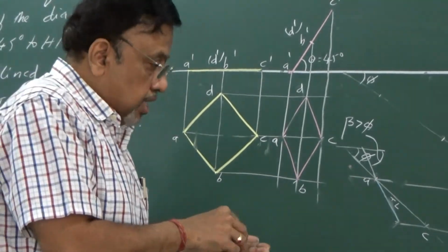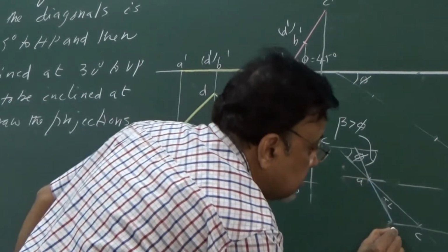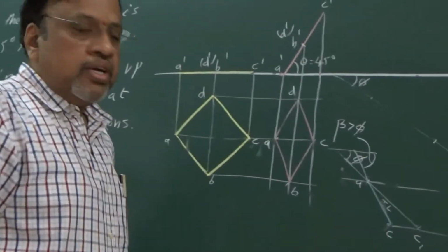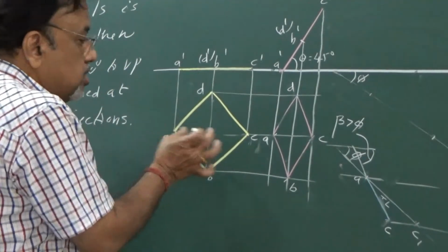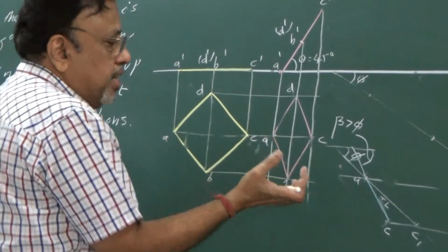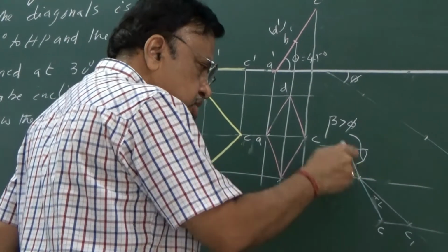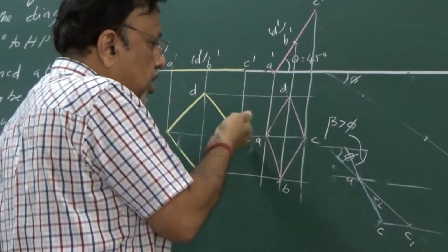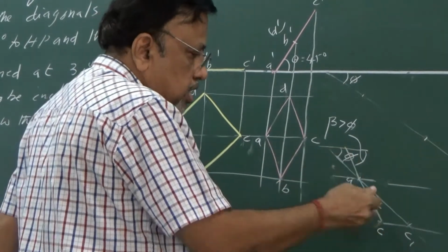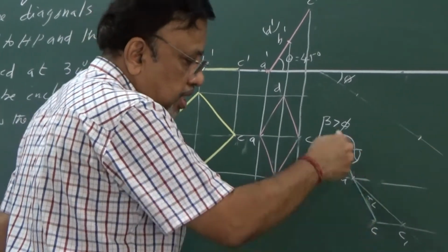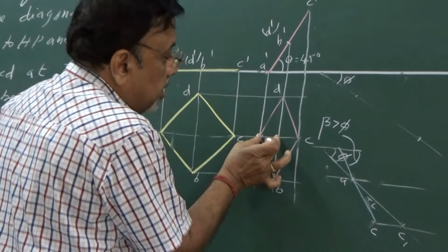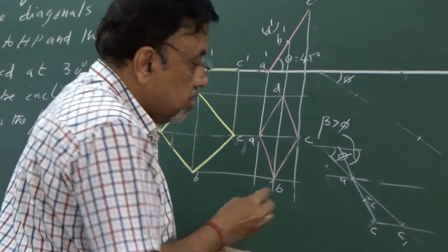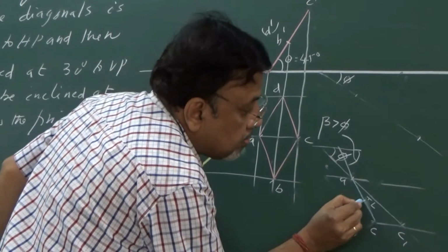So what I do here is, I will consider this to be AC, let us say AC1, because anyway this is the true length. So let us say this is my AC. Now this is the center point. Only thing is, I need to draw everything based on this reference line. Here all the lines are perpendicular to this. The same thing, the other line is perpendicular to this particular AC. Now let me take this length and put it here. Then get that line.